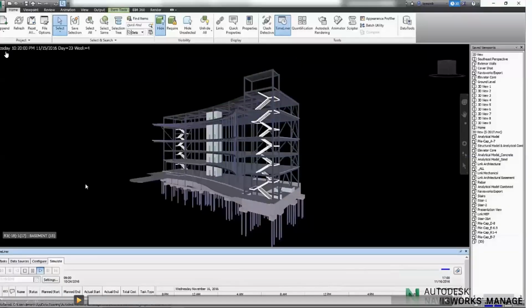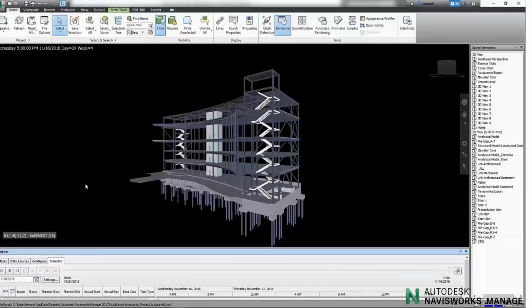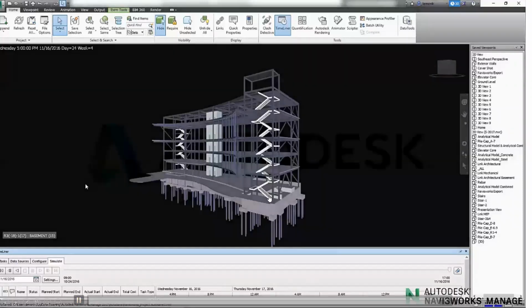And in the top left, you can see every day, time, minute, hour, exact number of week that this is and when it's happening. And this allows you to see how the building is going to be constructed before you've even broken ground on site as well. So again, being able to do this with a client, particularly from an architectural point of view, in my experience, I've seen that architects are generally the BIM coordinators on project. They're generally assigned these roles, and you're usually charging the client an additional fee for that BIM coordination role. And Navisworks will become one of the primary tools for that. So being able to do something like clash detection or 4D timelining, you're adding a lot more value to that service that you're providing.